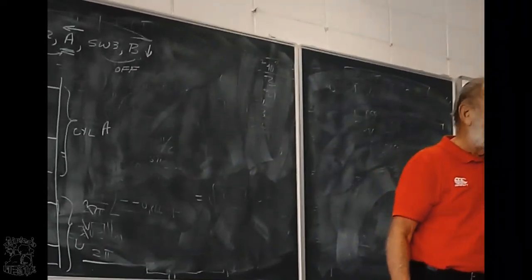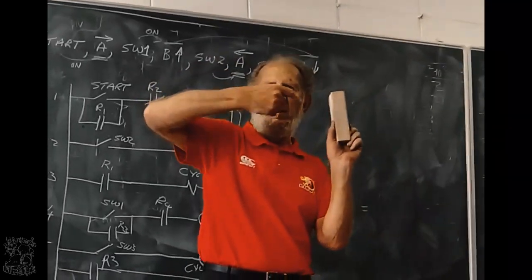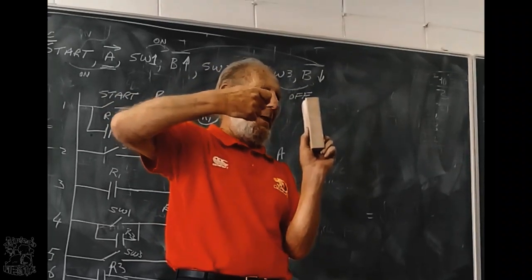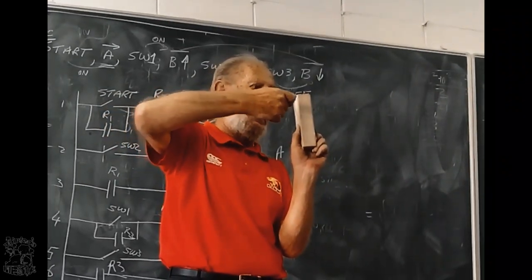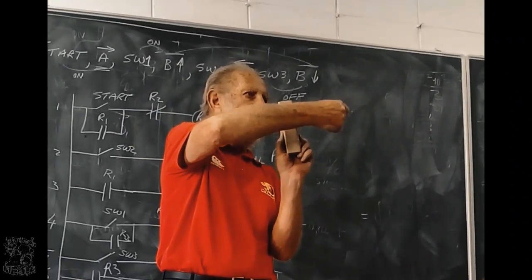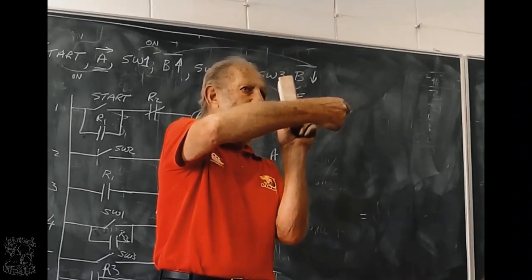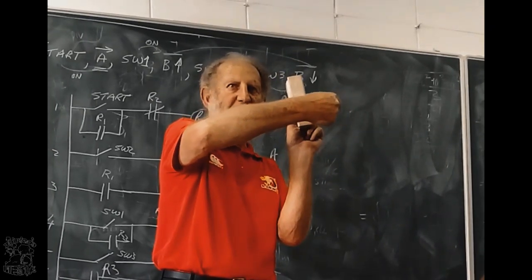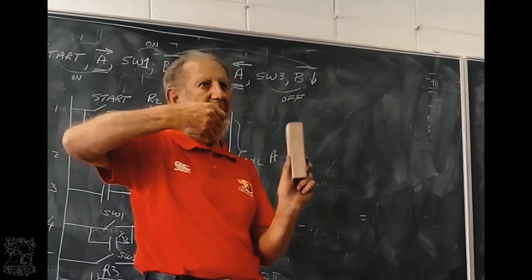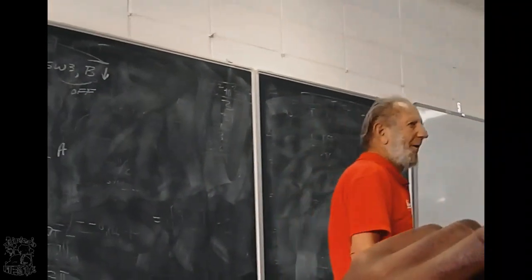Must I show you again? Cylinder A is here with the cutting tool. Cylinder B is down here. I press the start button. Cylinder A gets power. It cuts the top groove. It comes out here, it touches switch 1. Switch 1 puts power on this cylinder, it moves up. It touches switch 2. This one loses power, it comes back. It touches switch 3. This one comes back. I take the job out, I put the new job in, press the start button.